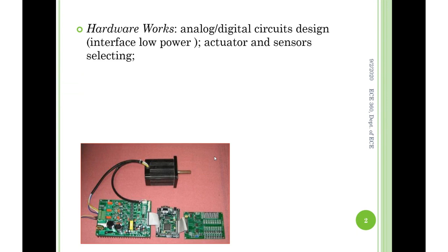In that environment, you're programming your controller in C or C++ or embedded C. Nowadays, the language for microcontrollers is mainly embedded C. Then you program in the computer by keyboard, and the programmed code, the algorithm, is compiled and executed by the CPU over here to generate a PWM signal, feeding the power board.